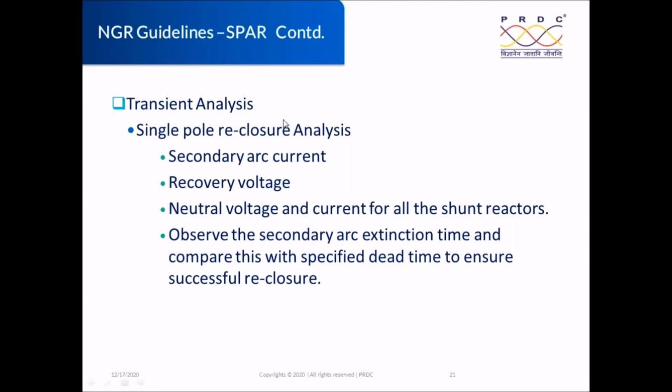So for the selected NGR value, we need to model the arcing fault, so that the arcing fault extinguishes automatically, which will ensure successful reclosing. If it is not getting extinguished, then maybe the initial value is not sufficient. Maybe we may have to go to the next higher value where we will get it, because this is our main objective, right? To have the successful auto reclosing phenomena.